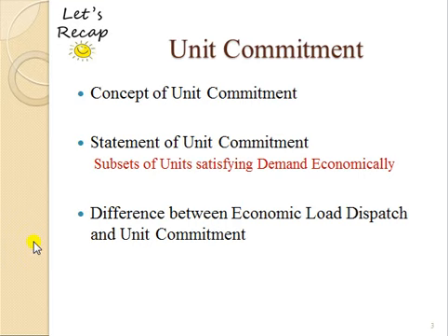So let's understand what is the concept of unit commitment. I would like to focus on the word commitment basically. The meaning of commitment is to bring any power generating unit into operation. So when you are taking any power generating unit into operation, all the technical procedures of synchronizing that unit to the grid and start delivering power to the grid is to be done. So this typical operation is being called as commitment. So whenever you are taking any unit out of operation, that you will decommit the unit.